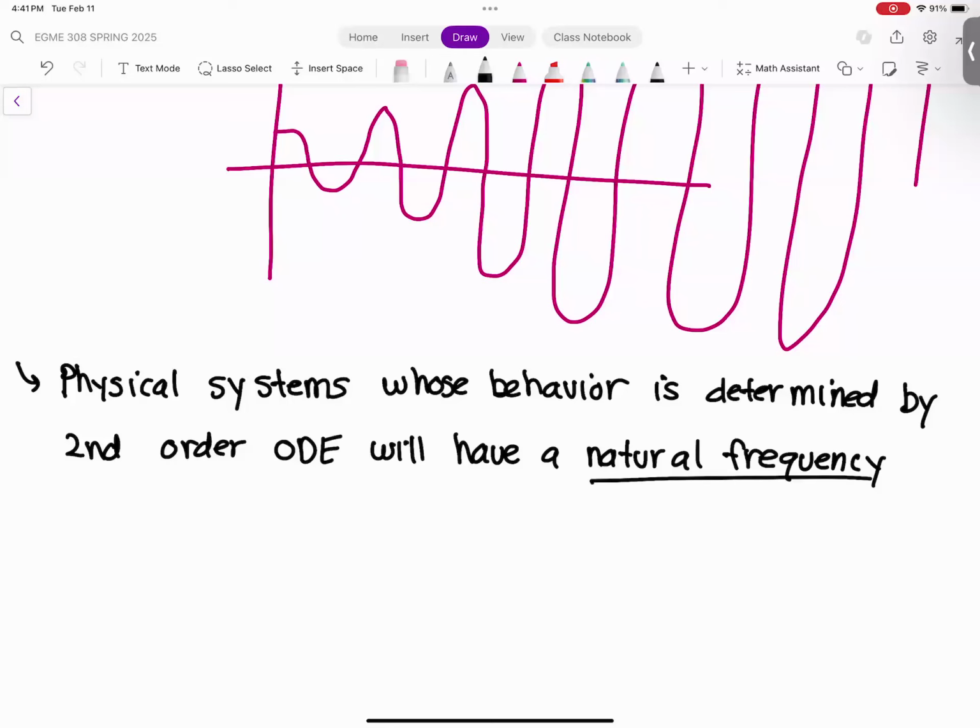But in order to get vibrations, you have to provide it some kind of stimulus. So the best way to do it is to perform what I call the flick test. The flick test is that you take an object and you just flick it, right? For those of you in the class, you can see, I'm flicking this thing, and it's hurting my finger a little bit, but as I'm flicking it, this projector thing is vibrating a little bit, right? It doesn't last for very long because there's a lot of damping in the system. My fingernail's hurting, but you can see that it does vibrate a little bit.